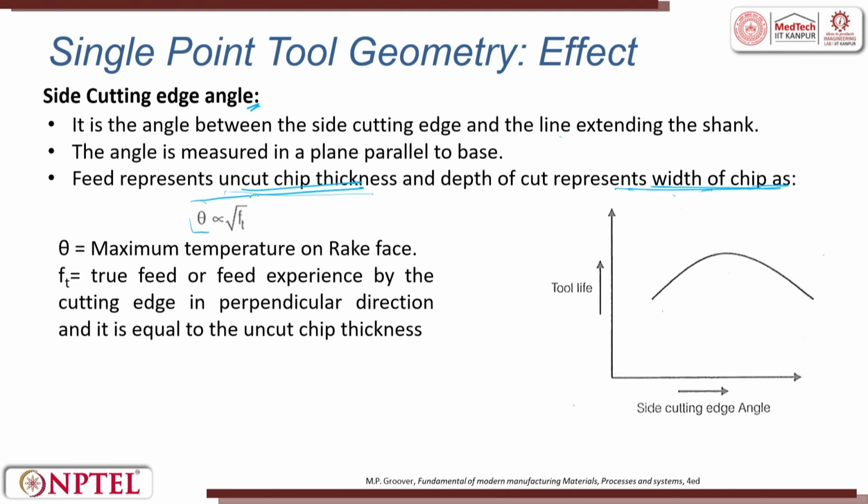Here, the temperature is directly proportional to the root of the feed rate, whatever it is. If you look at the side cutting edge angle, again it follows the same trend, wherein at one particular angle you have a maximum tool life and then a reduction on both sides. Now let me introduce the terminology F and D.